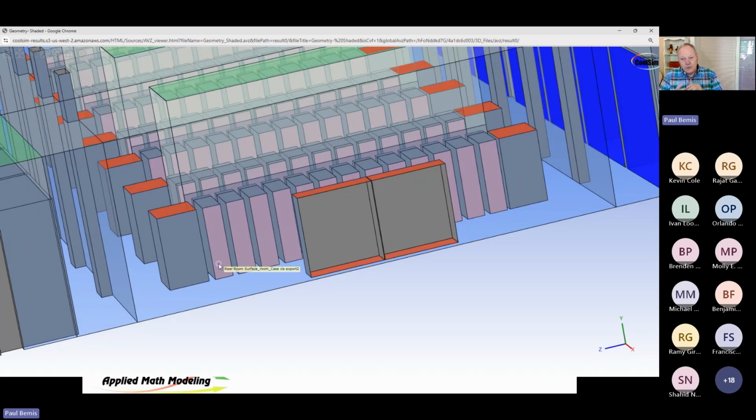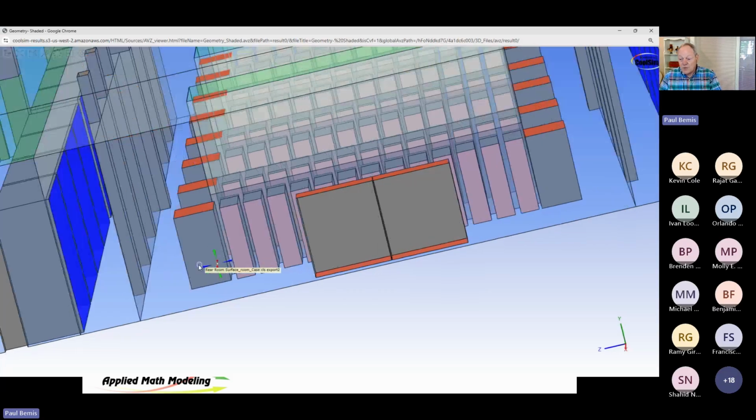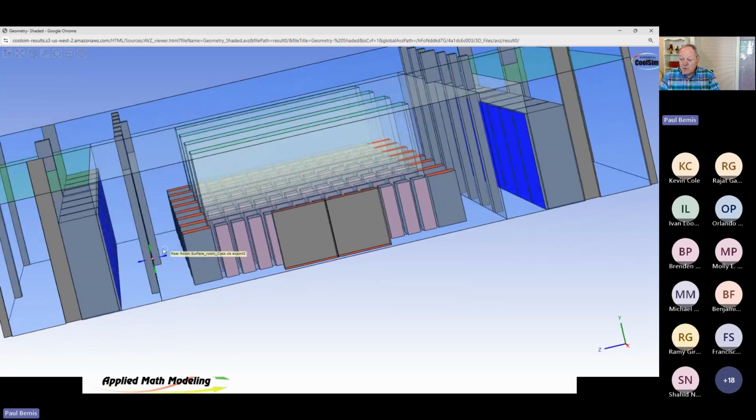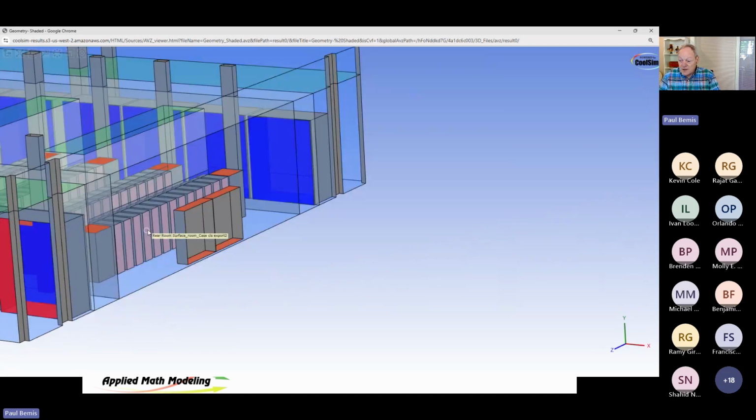But 44, 45 is about the maximum you're going to be able to dump efficiently in a data center for air cooling. And so you really can't use a raised floor data center in this because there is just so much air that your plenum would have to be extremely deep in order to keep that velocity from being too high. And that's expensive. So the alternative is fan wall units.